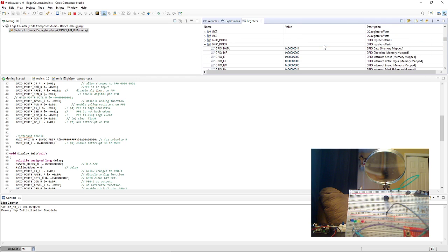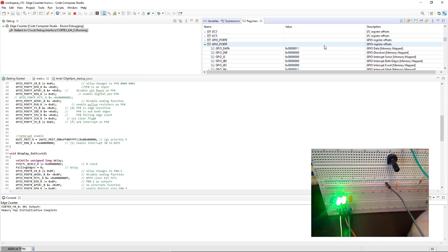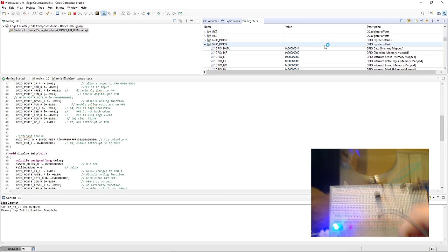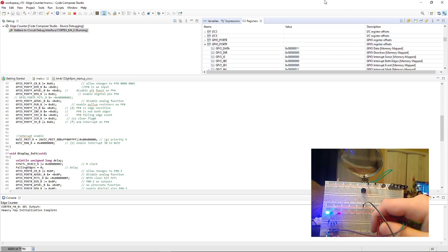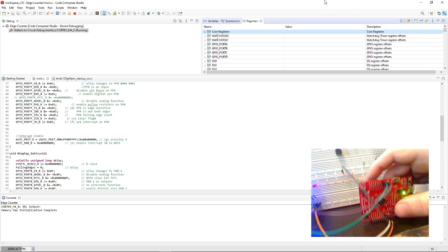But that's all I wanted to show for today, is just that this code does in fact take a number in and counts up in binary. Now keep in mind this is in binary, so that's representative of 4, and there's 5, and there's 6. Really cannot see the different LEDs. I should have spaced them a little bit farther apart. But we count all the way up to F, with the red LED being the least significant bit and blue being the most significant bit. And those are just wired up from port F like you would expect.